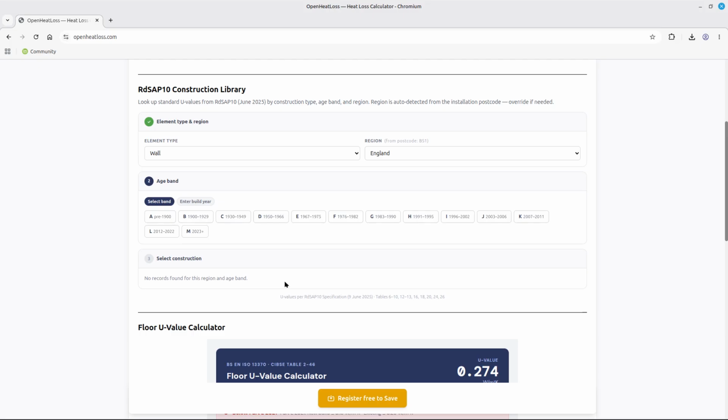What I recommend, though, is that if you have U values specified by an architect, by building drawings, or any other references by a professional for your house, go by those. But otherwise, you can very much use this based upon a little bit of guesswork and a little bit of surveying of your own house, like measuring the wall thickness.